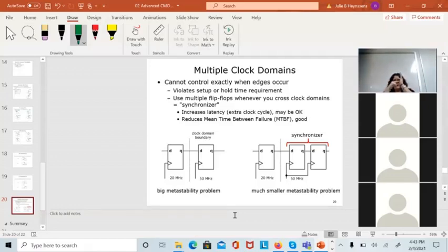So it hits the array within 200 nanoseconds, which for us was 2 clock cycles. I had to read out the address of where the particle hit by looking at a threshold detector, subtract 5 from it, and then read out a 5x5 window around this device, repetitively really fast. Because we could read out, he could take pictures of this high energy event happening.